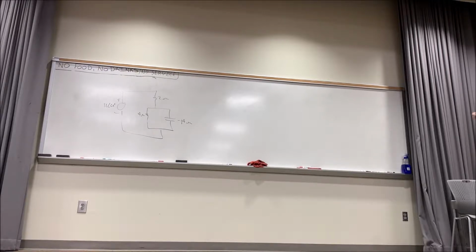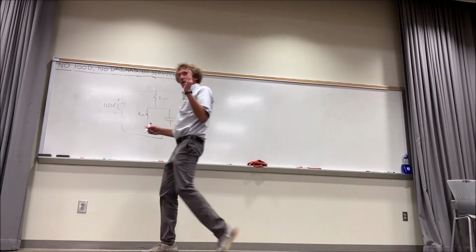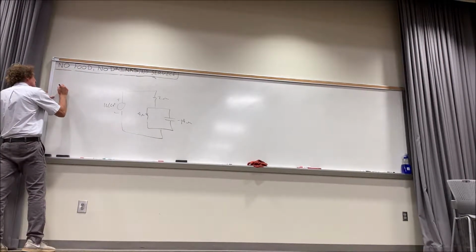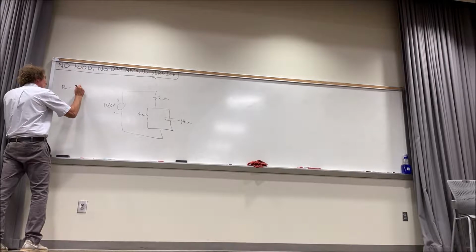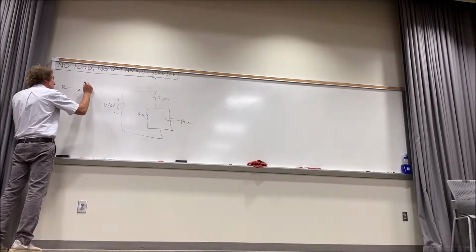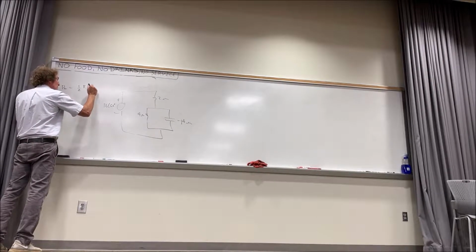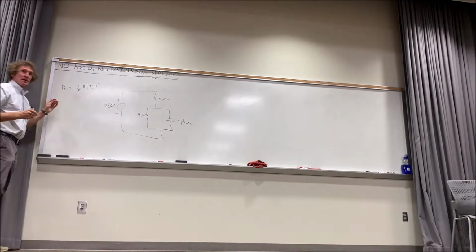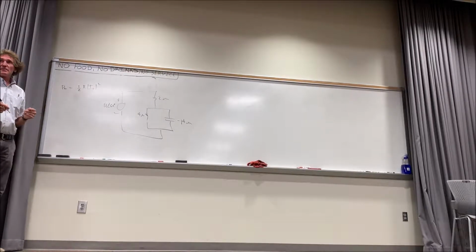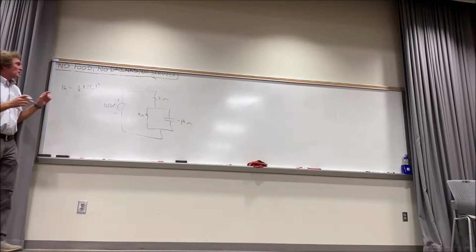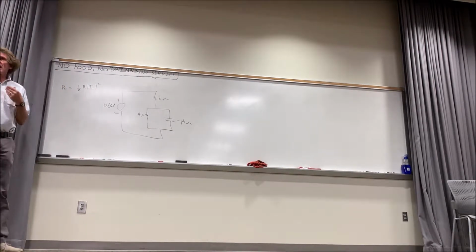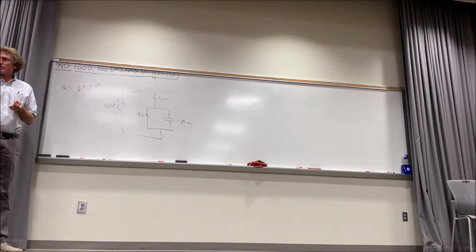If we're doing this problem and you want the power in a resistor, if we're talking about peak current, the average power dissipated is going to be 1/2 times the value of the resistance times the magnitude of the peak current squared. Y'all with me on this one? This is standard. You can put an M here; I think some of you are used to seeing M as magnitude. It's the peak value, the coefficient of the cosine waveform.